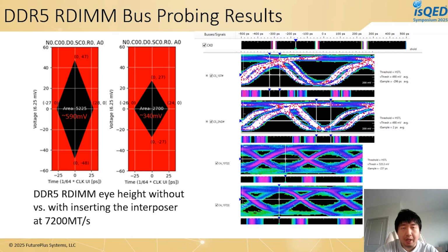On the right is the eye scan we got in the logic analyzer software. Remember that these are the QCS and QCA outputs generated by the interposer RCD. So they have very big eye opening and the full voltage swing, but these eyes cannot represent the signal integrity of the bus. But they will provide all the information of the bus when decoded, assuming all the signals were captured correctly by the interposer RCD.